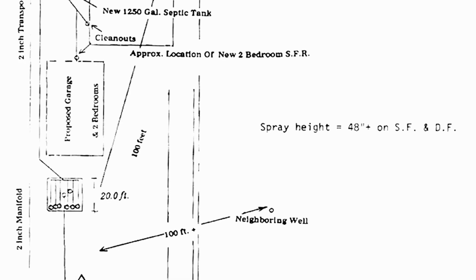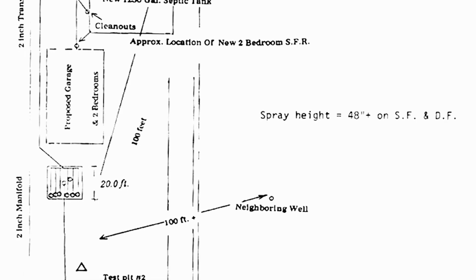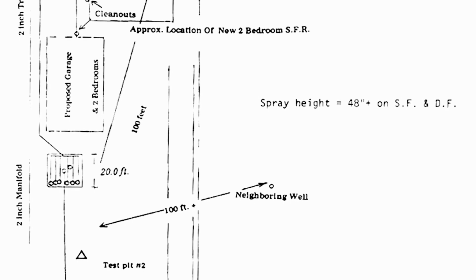Septic systems need regular maintenance just like your car or home. First of all, you should know where all the components of your system are located on your property. An as-built or record drawing is a technical diagram of your septic system. For Baltimore County residents, well and septic information is maintained by the Department of Environmental Protection and Sustainability, and records for your property can be obtained by making a request through the Groundwater Management website. Record drawings are not always accurate, so make sure you verify it's correct.